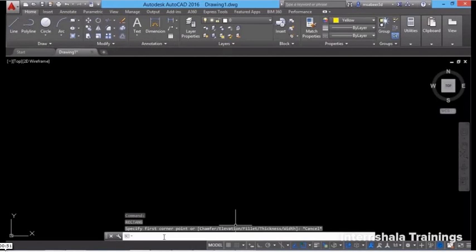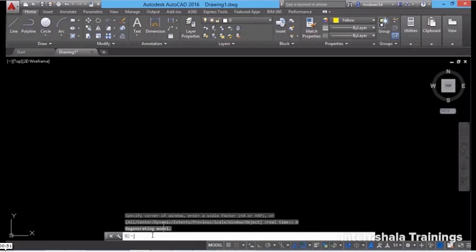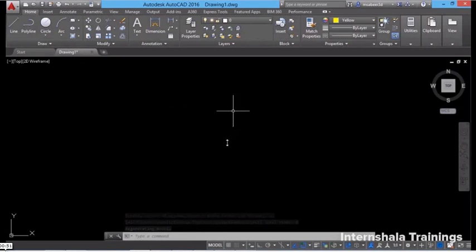So let's give the limits command in AutoCAD to get these limits on the screen. I'll give limits, and the lower left, when I am asked, I'll give minus 60, and the upper right, when I am asked, I'll give 60, followed by Z for zoom, and I'll type the letter A, or I'll click on all to get the limits on the screen. Obviously all the 4 quadrants must be in the screen, but the origin still remains here.